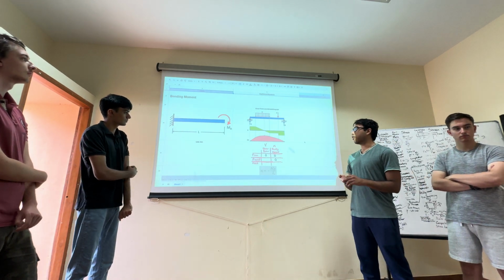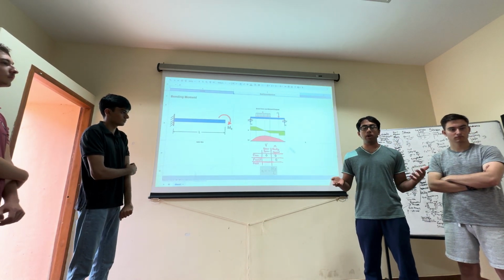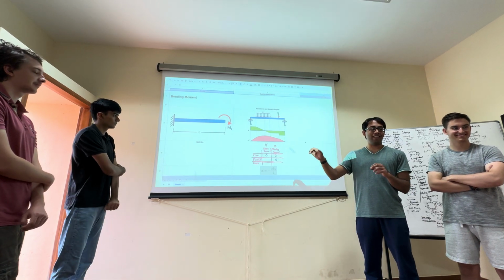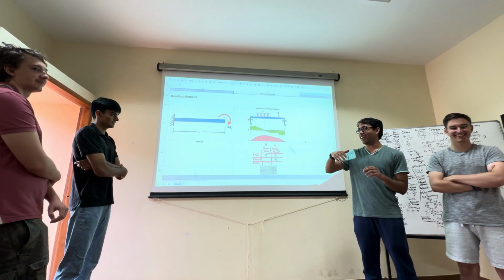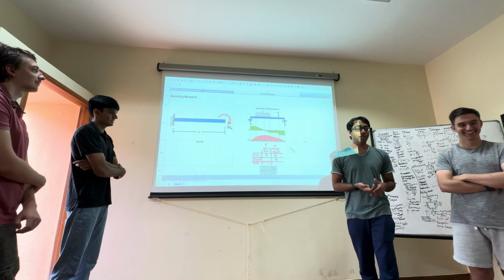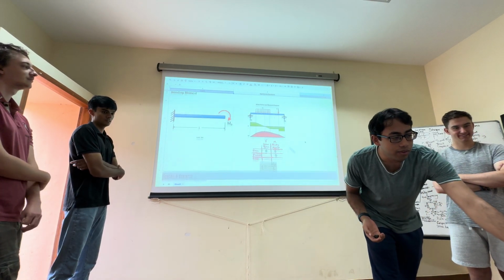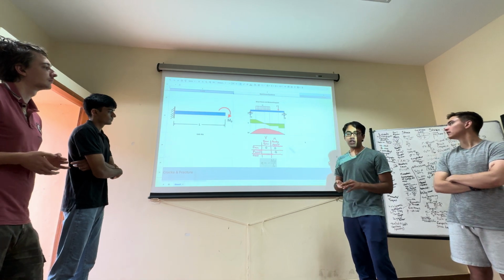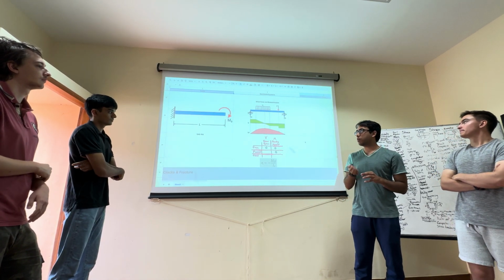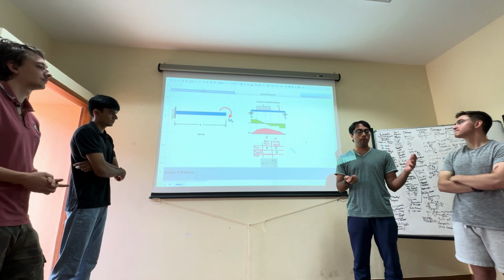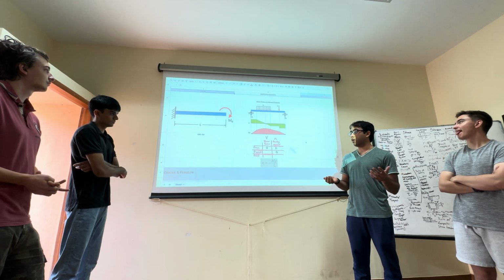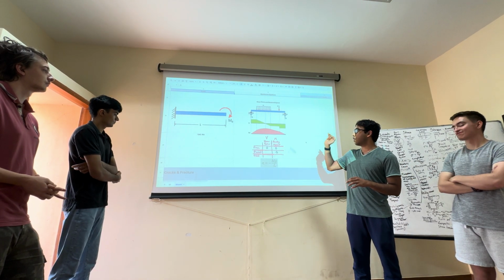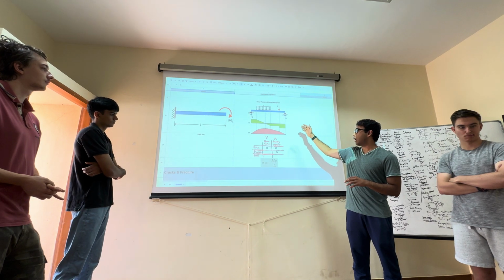So of course, another form of a load would be a moment, and we actually improved this picture from last time, where you'll see now the moment is at the tip of the bar instead of at the wall. So that's better. But we still included this diagram to the left or to the right, where we're basically trying to show this relationship between the applied load, the shear force that's created, and of course the bending moment, where they're all basically the integrals of each other. You can see that based off the graph, we'll see that it continues down.